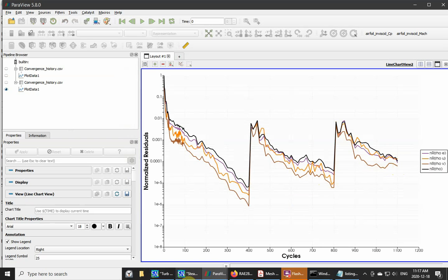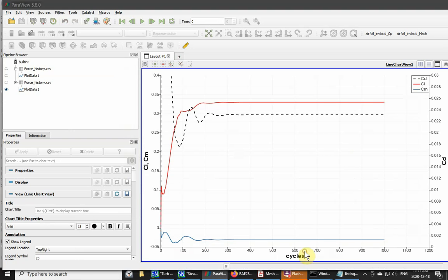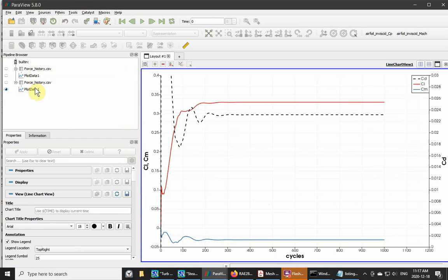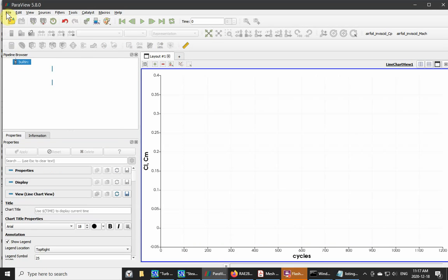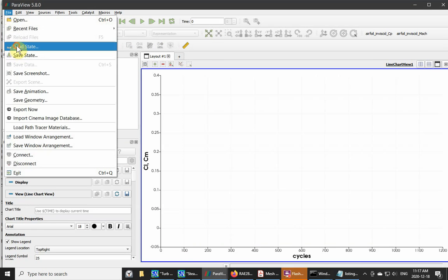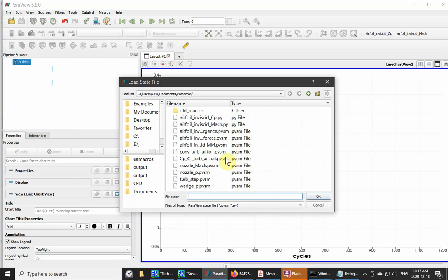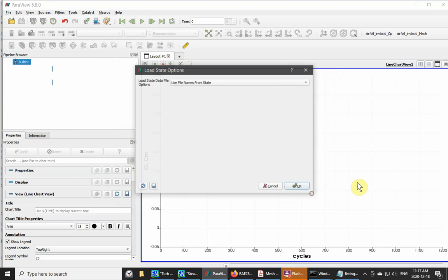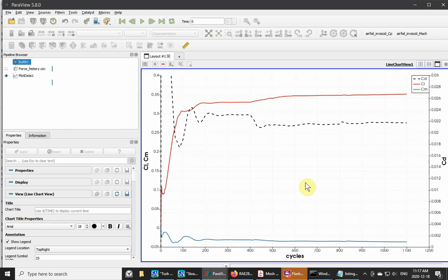And the forces, you can see here, approach steady state on the various grids, and the values of lift and drag and pitching moment are very close on the intermediate grid and on the final grid.